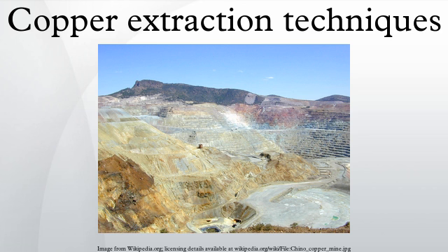A key objective in the metallurgical treatment of any ore is the separation of ore minerals from gangue minerals within the rock. The first stage of any process within a metallurgical treatment circuit is accurate grinding or comminution, where the rock is crushed to produce small particles consisting of individual mineral phases. These particles are then separated to remove gangue, thereafter followed by a process of physical liberation of the ore minerals from the rock. The process of liberation of copper ores depends upon whether they are oxide or sulfide ores. Subsequent steps depend on the nature of the ore containing the copper.